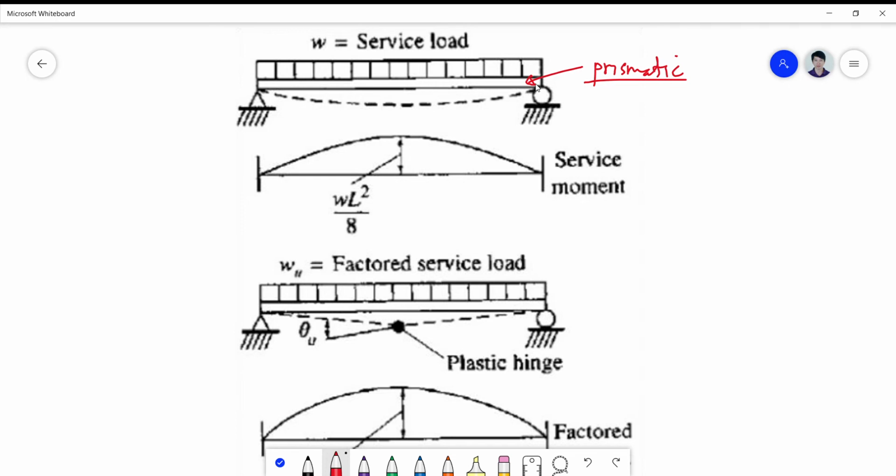Okay, yung sa elementary definition natin ng prismatic, shape lang ang sinasabi sa atin, no? But in my own opinion, prismatic property is in general the overall property, not only the shape of the section, but also the property of the material inside that section. I'm talking here specifically of reinforced concrete. Di ba yung section mo rectangular pero hindi prismatic yung reinforced concrete kasi yung bakal mo dun hindi naman pare-pareho yung sections mo, no? Okay, so that's just one of the many situations wherein being prismatic does not mean being of constant cross section.